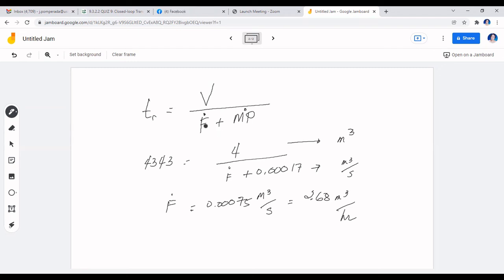So it has to be the, shall I say, the mix of the grown crystals plus the pure liquor flow rate. So the volume divided by this volumetric flow rate of the mixed product and the clear liquor will be giving you this time, which is 4,443.